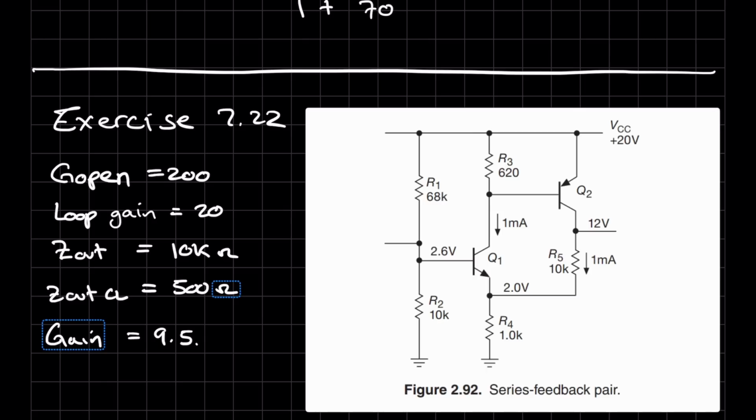So what we're going to do first is basically look at this circuit in a bit more detail. So you can see we have a potential divider over here, which is driving this transistor Q1. Now the circuit itself gives us the driving voltage over here, which is 2.6. You're going to have roughly 0.6 volt drop over here, which gives you 2 volts at the emitter junction of this transistor. This is the collector, this is the emitter, and obviously this is the base.